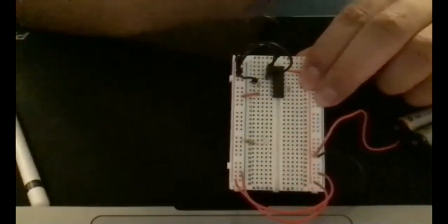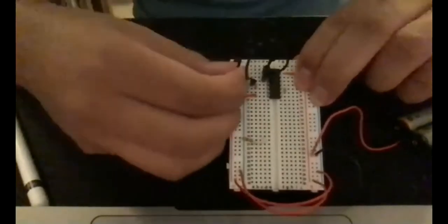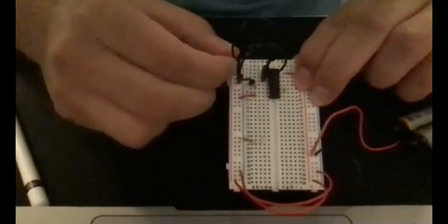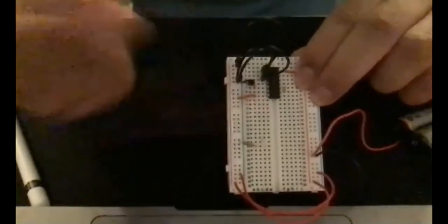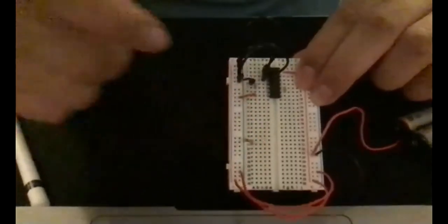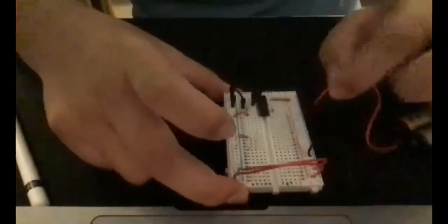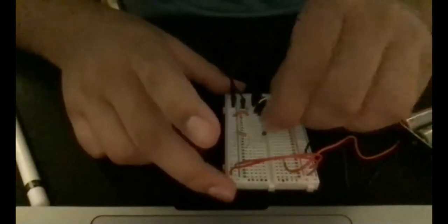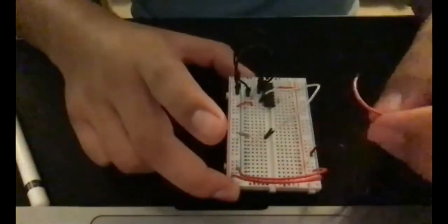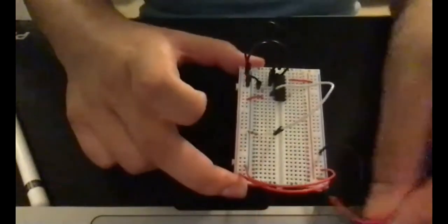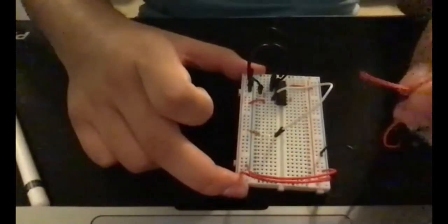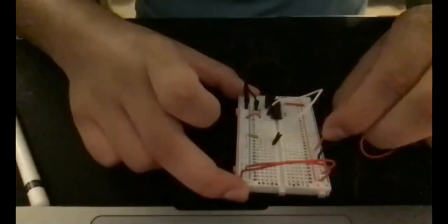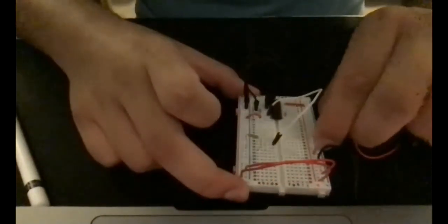So essentially what that would be doing is inverting our output. But see, one thing that we're missing now is that we have nothing here connected to the LED. So one last connection would be from this new output into the LED once again. So now it's still not working because there's no power being supplied to the circuit. So once I plug this in, the LED should remain off though.